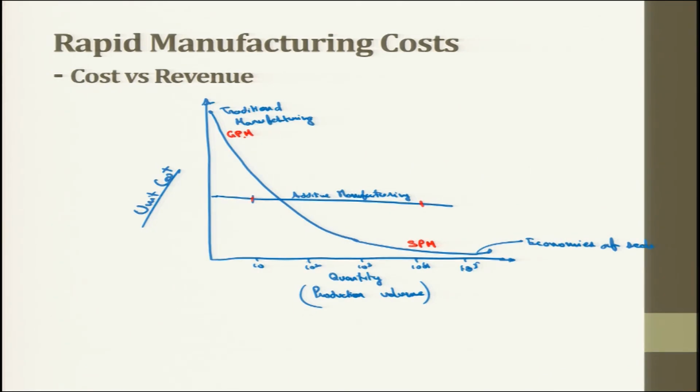In a bolt maker, the billet goes in and it first does a forming operation, the hexagonal bar is produced, then that is cut, threading happens, and it is produced in one go. So we use special purpose machines here, and the cost per unit is reduced. However, the fixed cost is higher for special purpose machines, but the overall cost is reduced per unit.